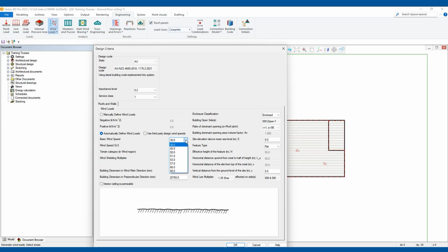So I'm in Brisbane, so that'll be 57 meters per second. And it's going to pick this automatically, which is your serviceability limit state. You shouldn't need to be altering this at all. If we pick another wind speed, that'll change accordingly. But we're 57 in Brisbane, and terrain category and wind region, we will be a 3B1. So 3, I think, being the terrain category, B1 is the region.